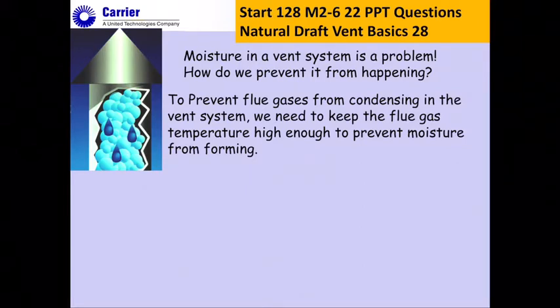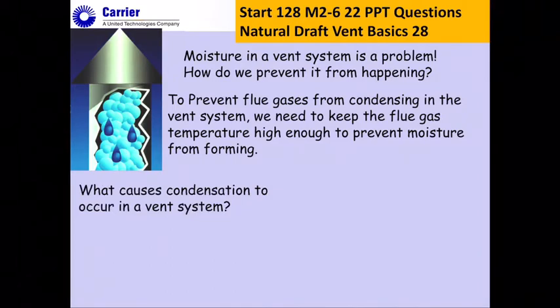I think to some extent we probably need to make sure we can get that flue gas temp high enough. And again, it's a little bit of a problem because the higher I make the flue gas temp to prevent the moisture from forming, the less the efficiency is out of my appliance. So it's a legitimate issue, but it is what I have to contend with. That means that if I want to get my flue gas temps lower to get more efficiency, my vent system had better be almost perfect.